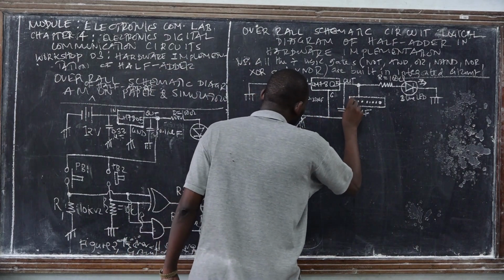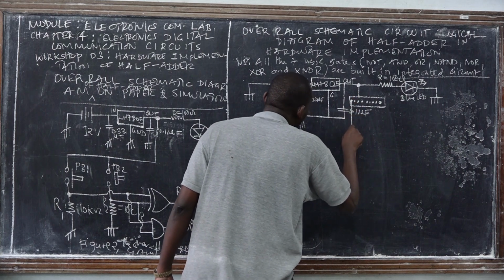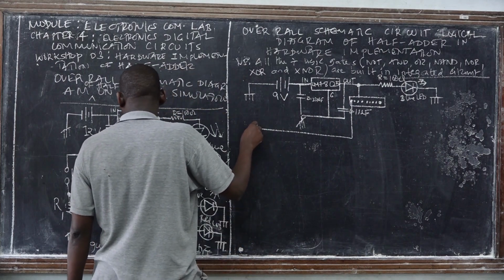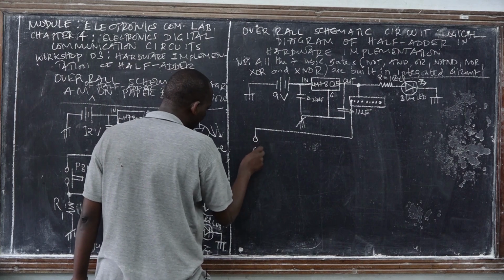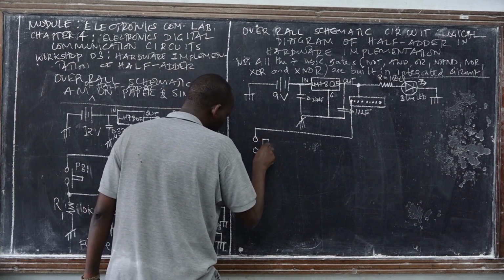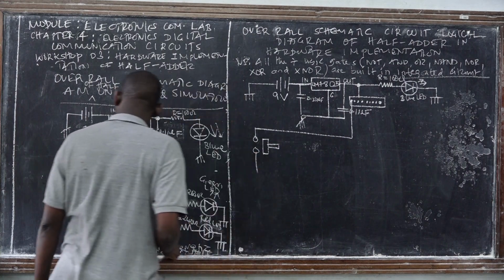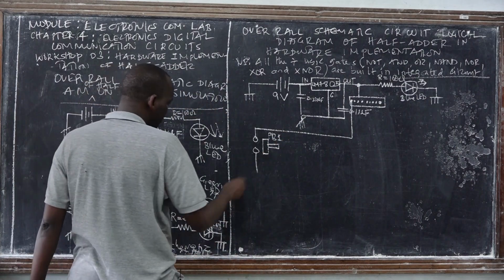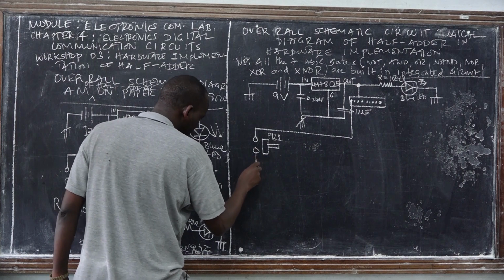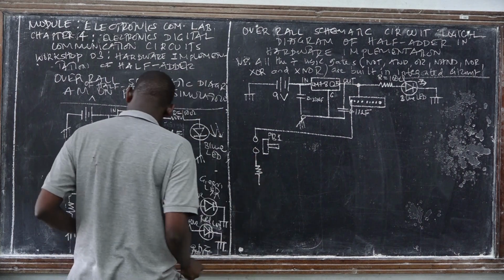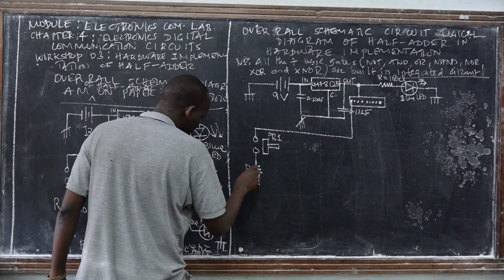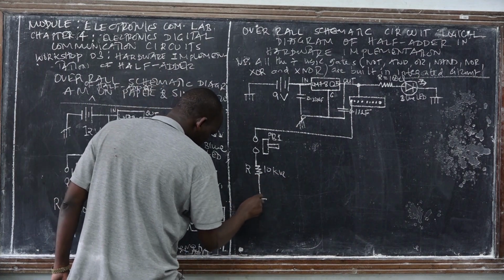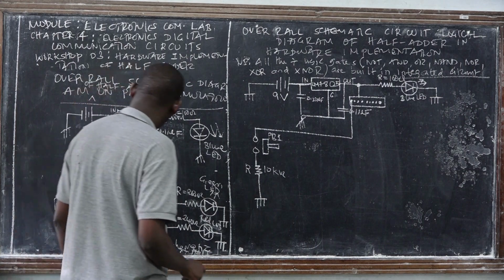So listen, you may use either copper or a wire to draw power into the breadboard and connect it into one terminal of the push button. So this is push button number 1. Then for this case we have a resistor, 10 kilo ohm. For this case we have ground.